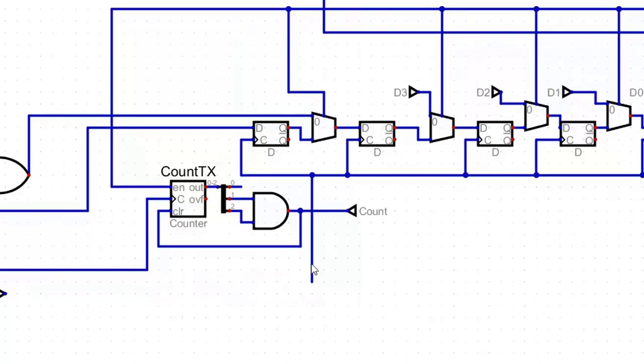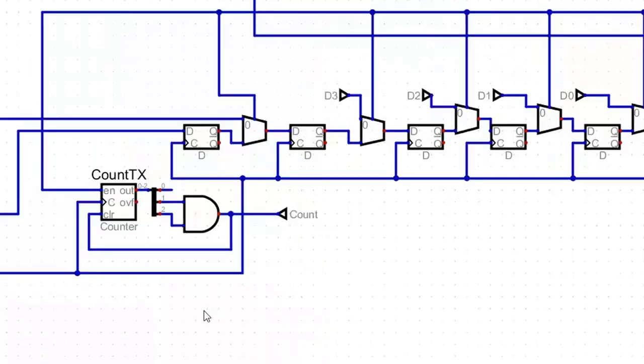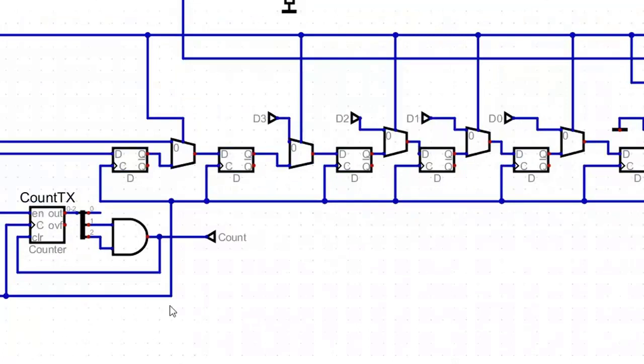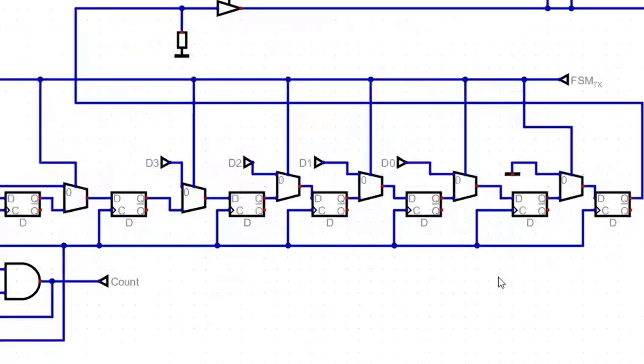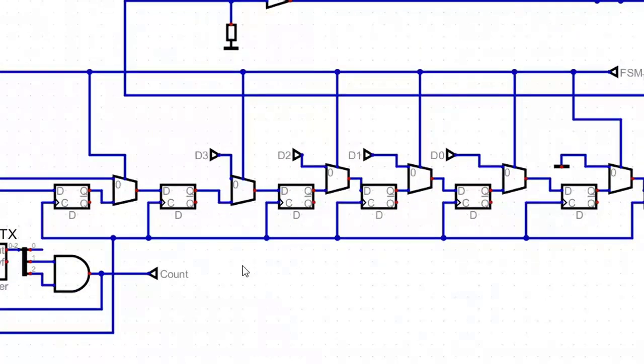Do you understand why you've just done what you've done? I don't want you to just do what I'm telling you. I want you to learn from the experience. Yeah, I did. What I was trying to do was create a clock enable so that my flip-flops would only start shifting when the FSM was there. But I see that the multiplexers do that already.